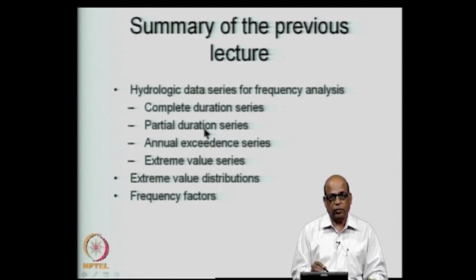Then we have the concept of the partial duration series, where you put a threshold value and then pick up only those values which cross the threshold. Let us say you put a threshold of 2000 cubic meters per second. So, whenever the discharge crosses 2000 cubic meters per second, we collect those values and then constitute a series and use only such series for frequency analysis.